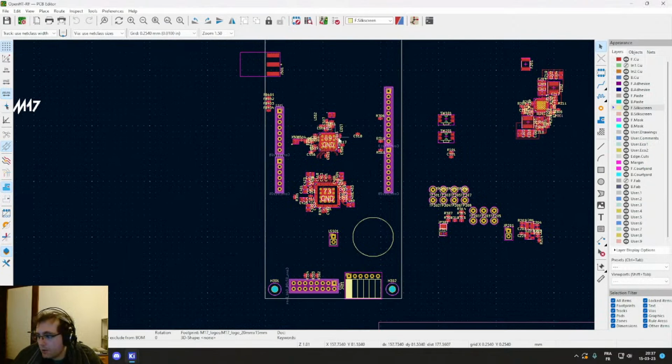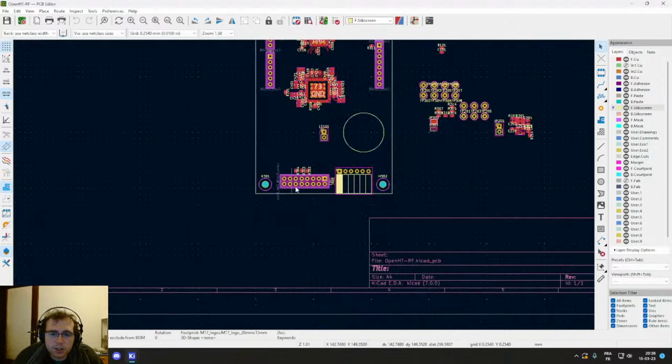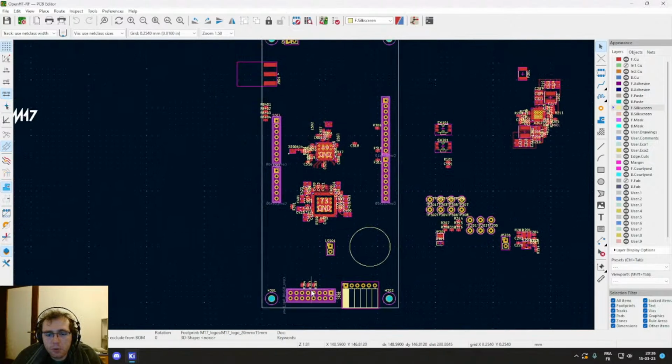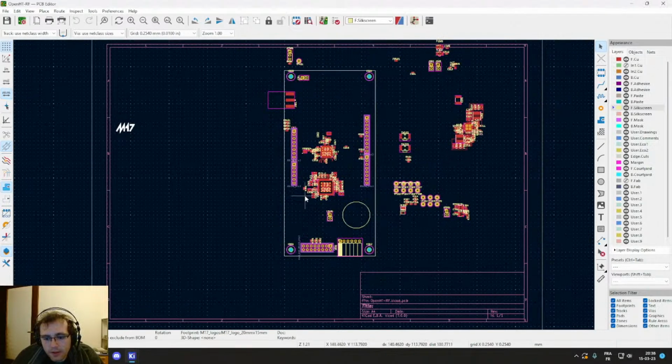And yesterday with KC1 Alpha Whiskey Victor, we made some mechanical design to find how we could fit the connectors on the board, because it turns out that ST Microelectronics do not give the accurate dimension and location of those connectors. Those four on the left and right, they are the Arduino Uno connector, which is easy enough to do, but if you want to align the mechanical holes and then the extension connector and bring together everything on a single board, which will align perfectly with the Nucleo board, then it turns out that it's harder to do.